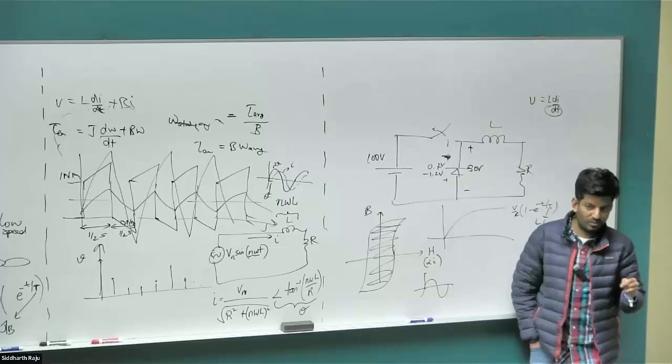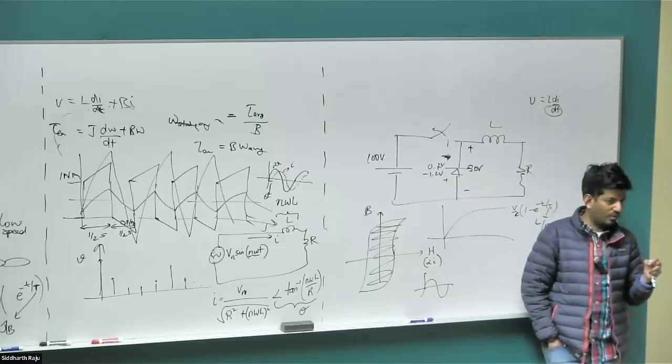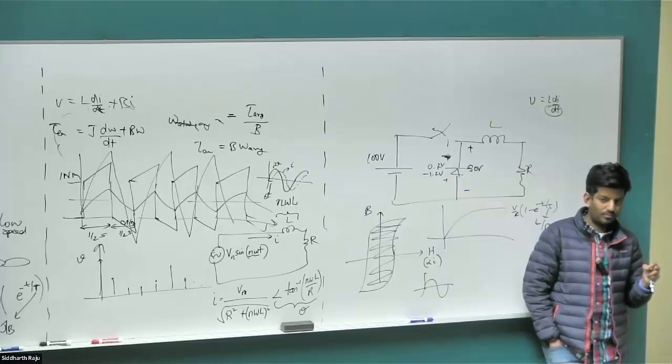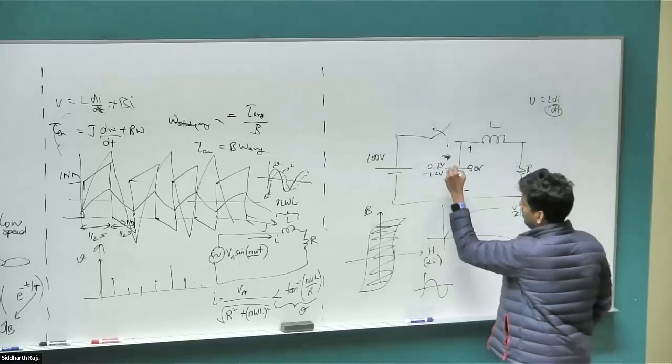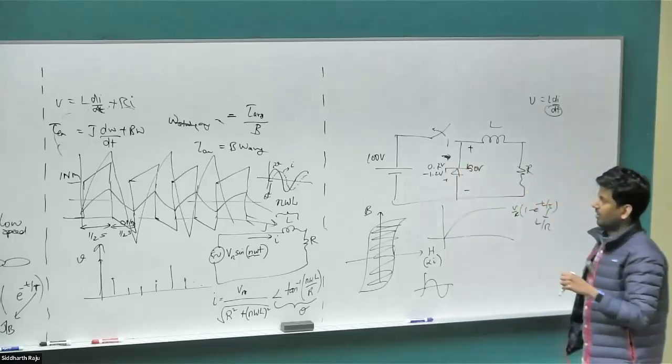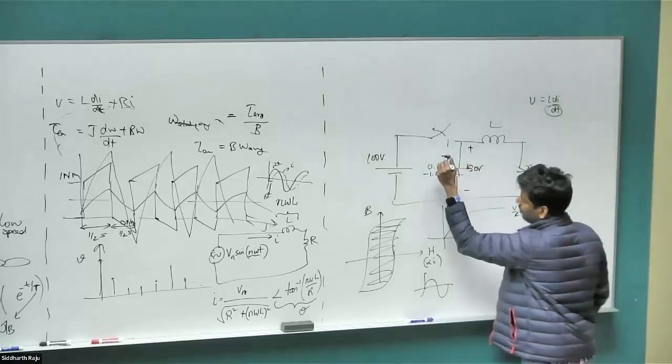There are two solutions that we discussed. What can we replace the diode with? Transistor. A transistor. Another solution? Schottky diode. So we can replace this with the Schottky diode, right? Which would have a low voltage drop, about 0.2 to 0.3.